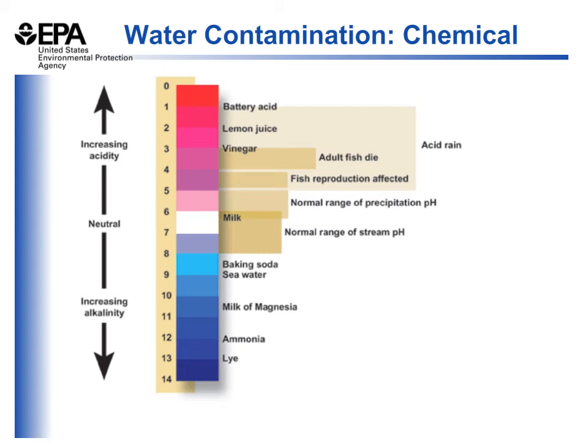pH is measured on a scale from 0 to 14, and 7 is considered neutral, or the boundary between acidic water and basic water. The lower the number, the lower the pH, the more acidic the water is. In many areas of the country, the pH of the water may be between 5 and 6. This can create corrosion within the distribution system and corrosion control practices are used to raise that pH to a more neutral level, typically between 6.5 and 7.5.